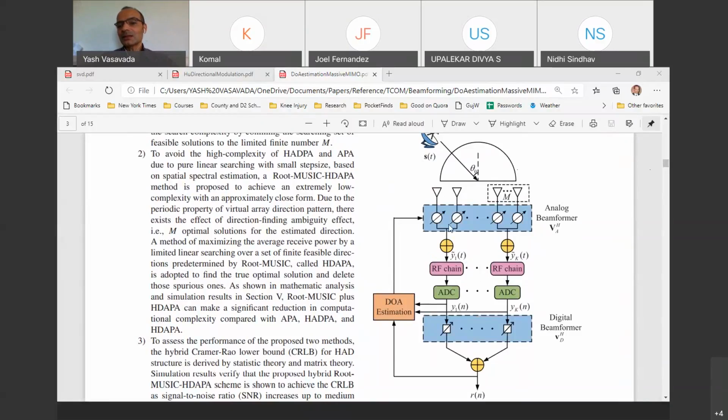And so the entire research activity that is going on in hybrid beamforming is motivated purely by economic terms. The reason why it is called hybrid beamforming is because this part can also be thought of as a beamformer, because they have these phase shifters. And remember, the single user matched filter is nothing but a phase shifter in the context of beamforming, and that can be done entirely in the analog domain. So this is the analog domain beamforming.